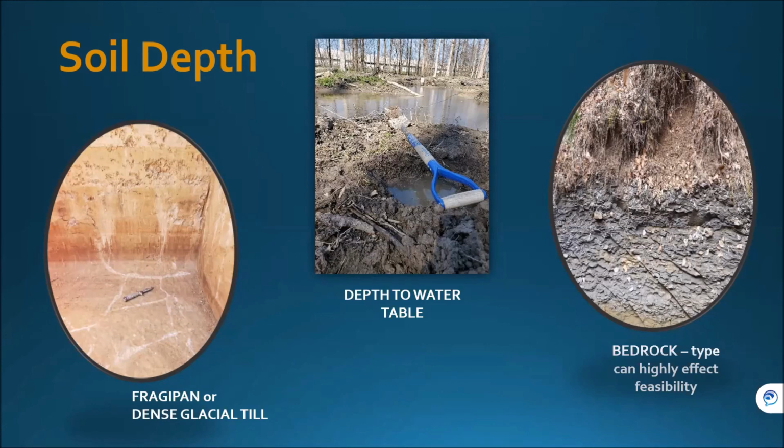Bedrock, usually in our wetland areas, is not shallow enough to cause any issues, but the different types, as I mentioned before, have varying degrees of feasibility. As I mentioned, with the karst topography, with the solution-dissolved limestones in the south and the sinkhole area, those probably are going to be really challenging sites to get to hold.